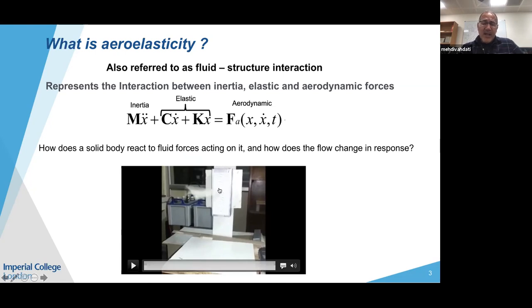And I have to say that most of the cases which involve aeroelasticity, you usually converge to a limit cycle. So the amplitude of the vibration is limited. And consequently, most aeroelastic vibration results in high cycle fatigue, i.e. you do not break something immediately. It starts developing cracks during the period of using that component, whether it's a wing or a component of the turbomachinery.